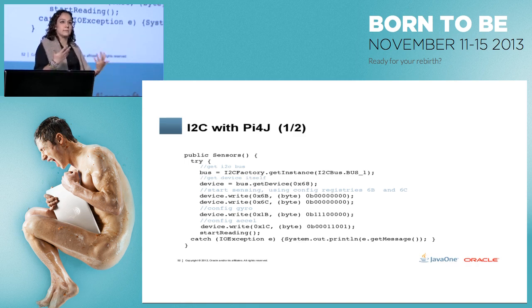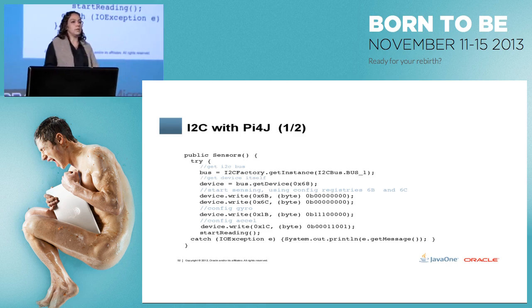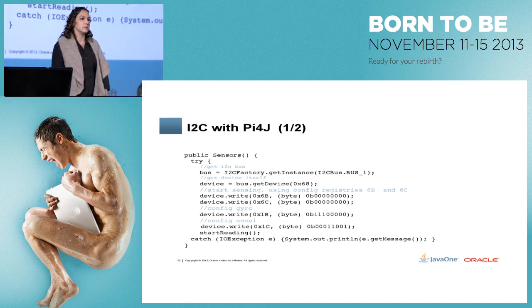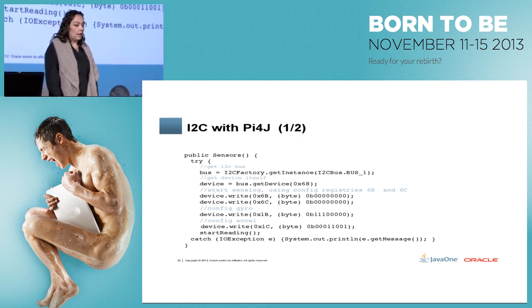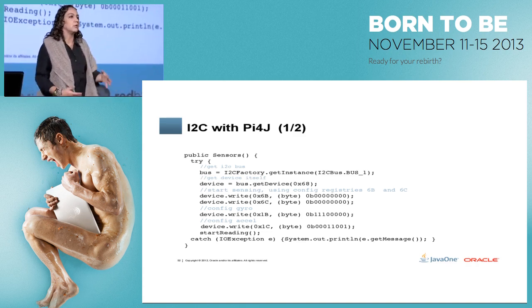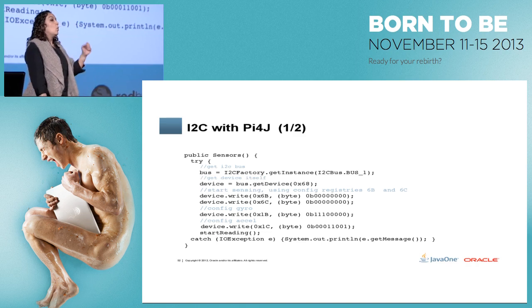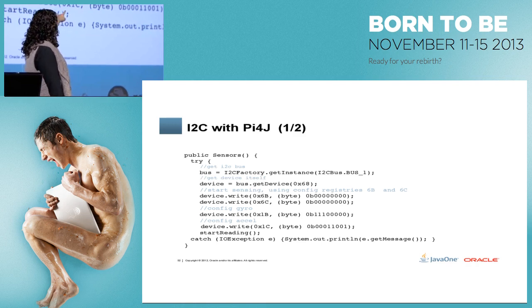I wanted to sense the movement, and I was getting 0. The document for these boards is normally around 300 pages, and all they talk about are the different internal registries and all the settings that you need to do. Well, for your board to start sensing, I needed to write 0 on those two registries. Before that, I couldn't read anything.